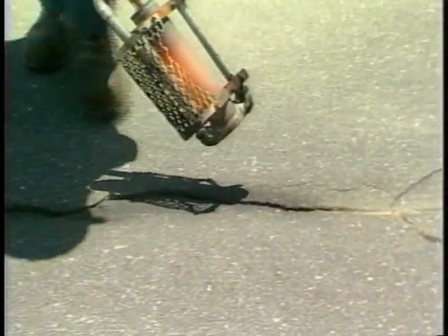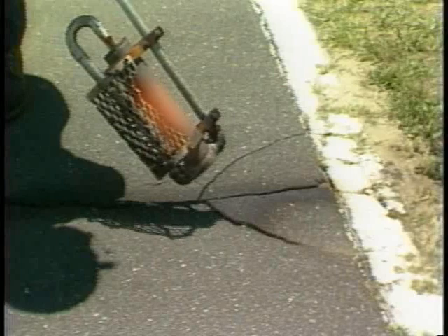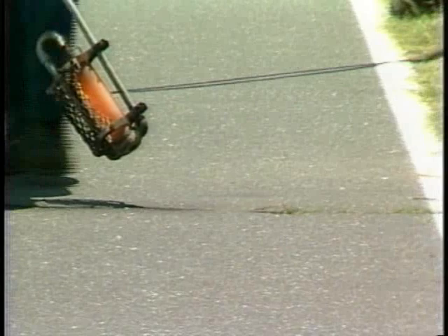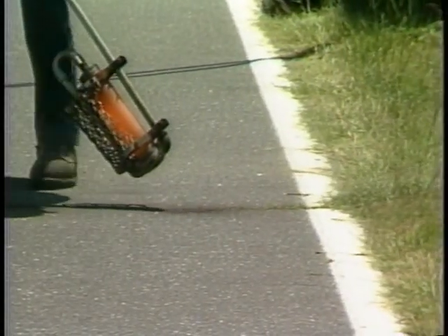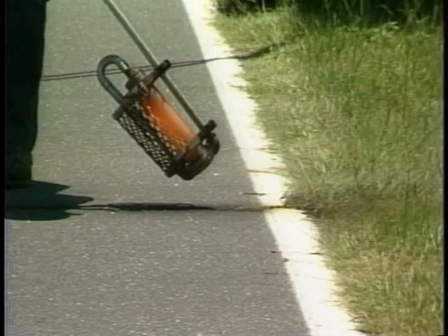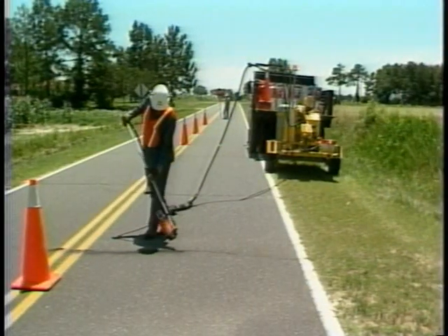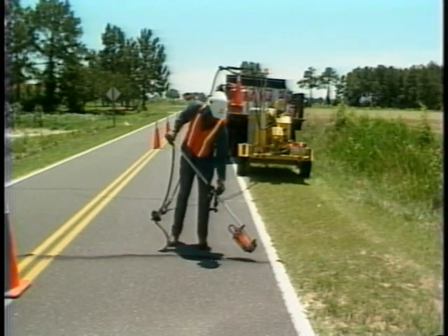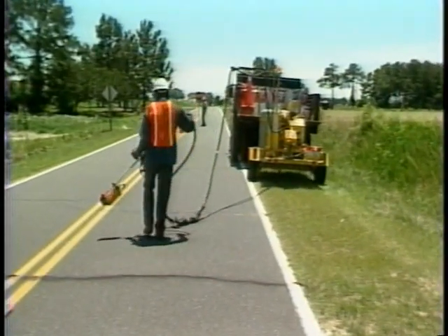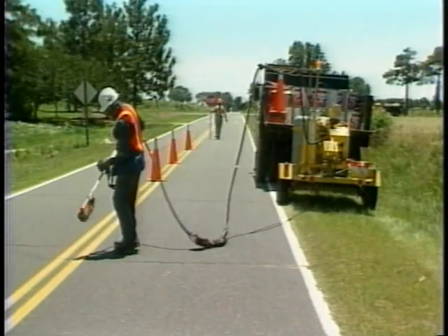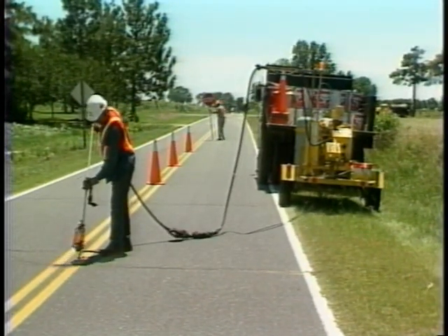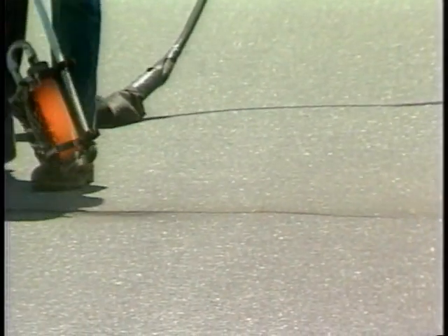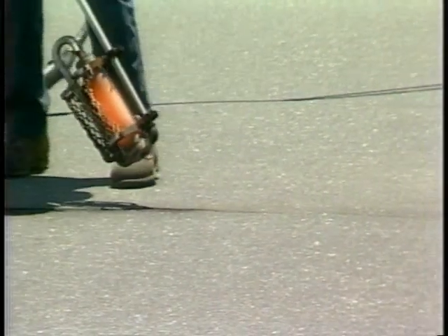In addition, the asphalt pavement is heated somewhat, and the asphalt binder is softened to aid the bonding of the sealant. The hot air lance also burns away organic matter in the crack that would interfere with the sealant bond. The operator is careful to keep moving so the lance does not burn and damage the asphalt pavement. The hot air lance ensures a dry surface for the sealant bond. Often the surface of a pavement appears dry, but moisture remains in the cracks below the surface. The hot air lance dries this latent moisture.